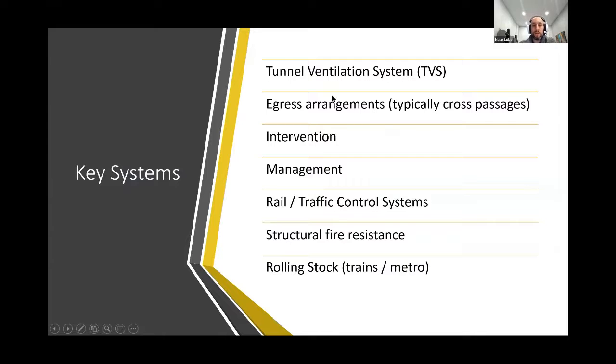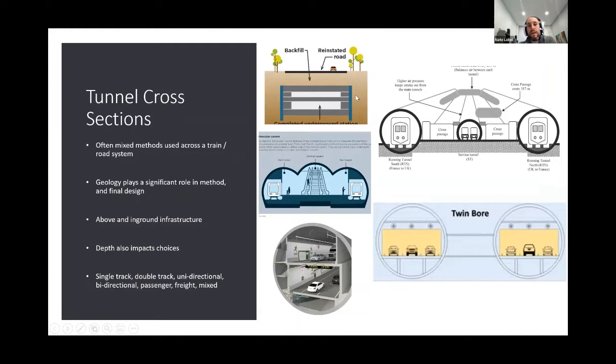Oh, sorry. This top one here is what the tunnel might look like afterwards from a cut and cover, much more of a square box. This is where you might have traffic, and this top one is where you'd run all the services. This is what we call a trinocular arrangement. This effectively is just where two bored tunnels come into a station, and the station has been caverned out.